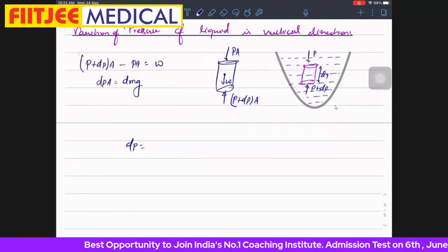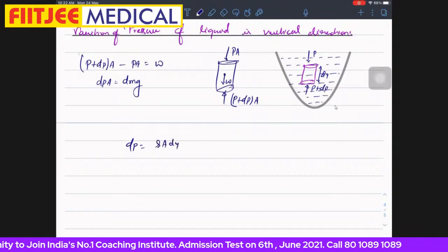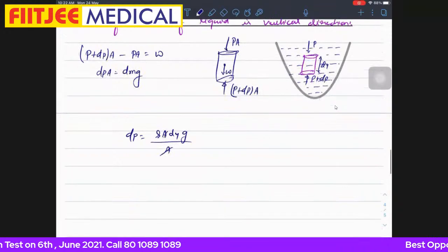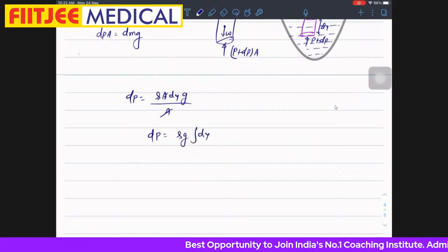So dp will be dm, which I can write as rho A into dy, into g by A. So dp I can write as rho g into dy.